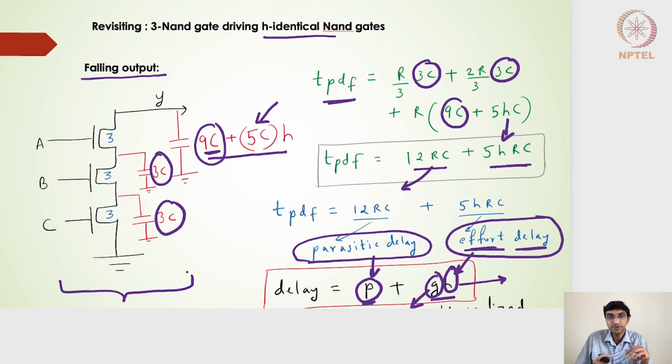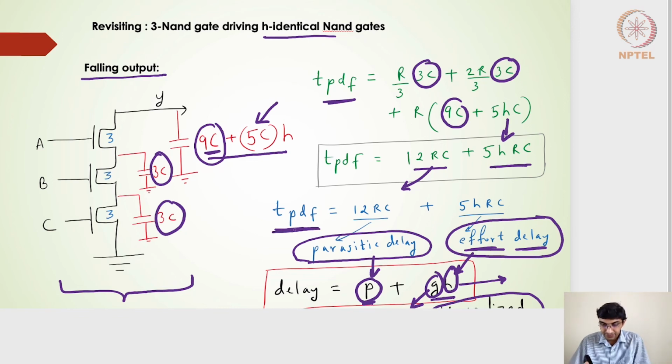The design circuit could be a 3-input NAND gate, 2-input NAND gate, 3-input NOR gate, inverter, and so on, and even combinational circuits, right? And I've stated here as normalized. Generally, when I get the delay parameters for a 3-input NAND gate or any other circuit, I'll get the propagation delay falling or rising. Generally, we normalize it with respect to the inverter's delay.